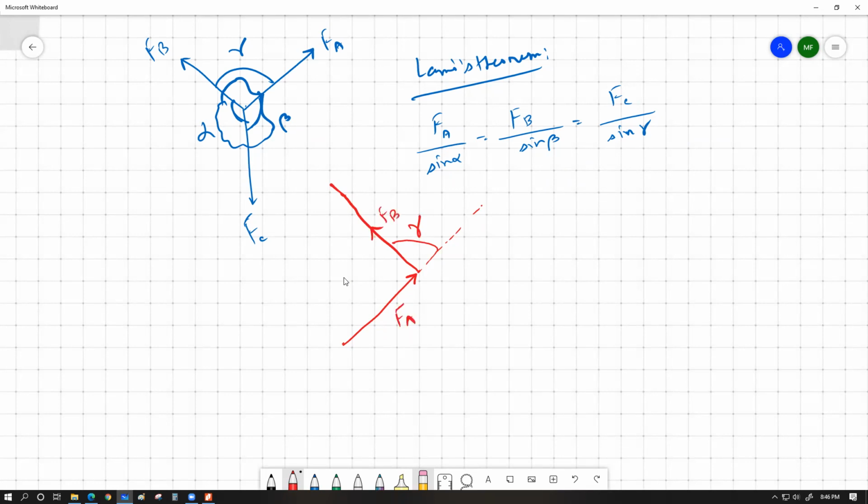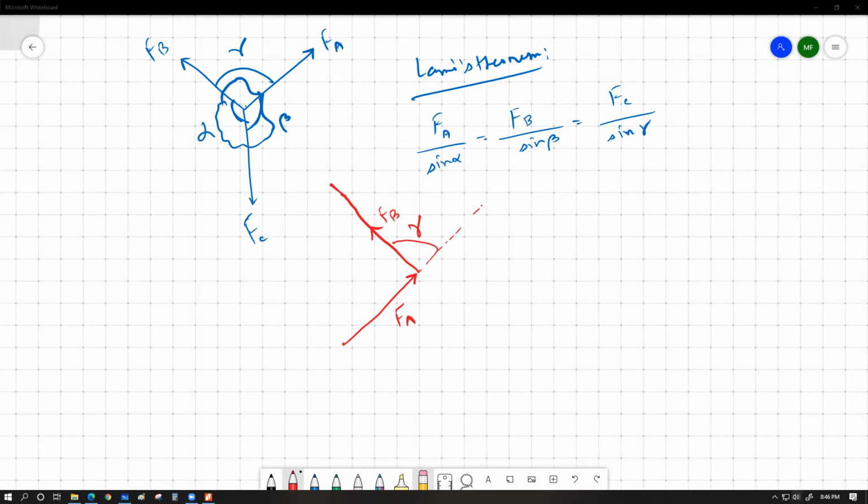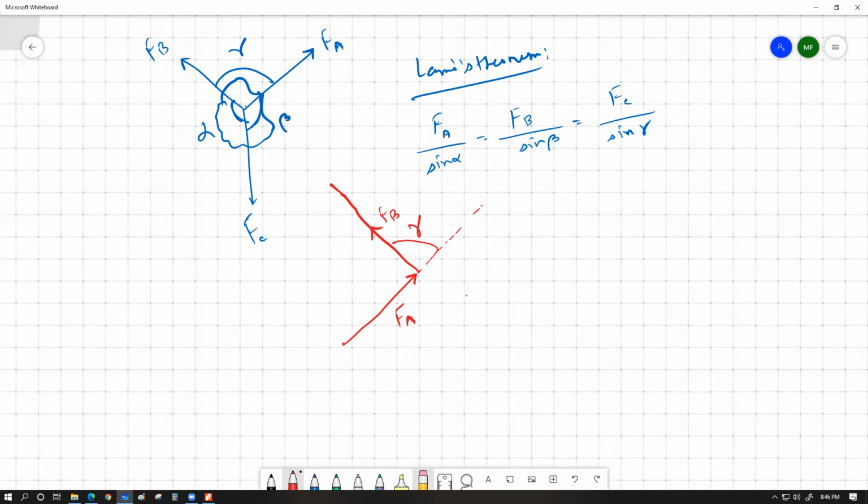See whether you understand this, where I drew the angle gamma. The angle between the FA and FB force, this angle is gamma. So the direction that FA is going in, FB is at an anti-clockwise gamma angle further from the FA direction. So this is the angle of gamma that is picked up from this position to draw the new element of FB. So I'm trying to draw a triangle rule over here, placing the vectors one after another. Then FB is going this way.